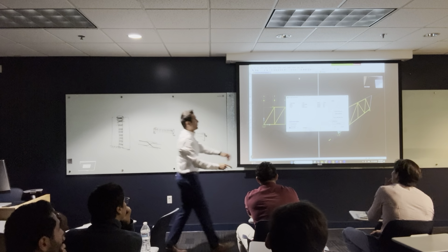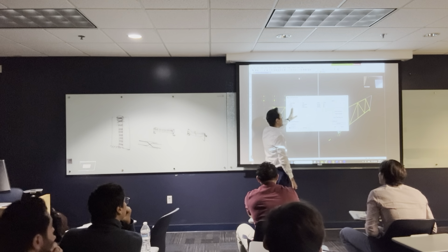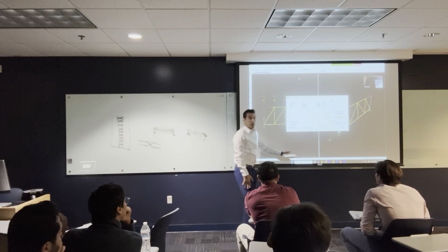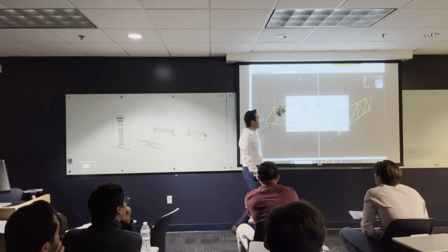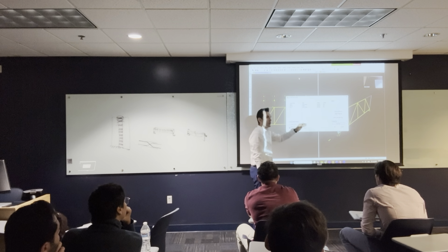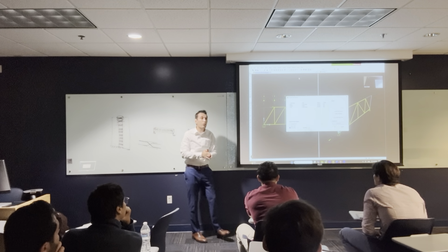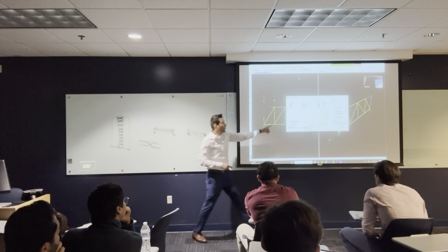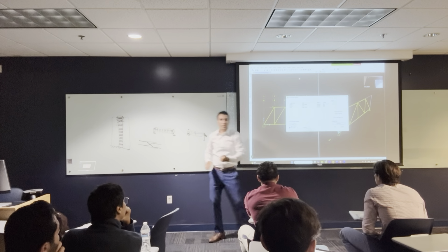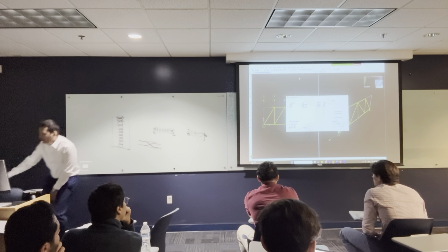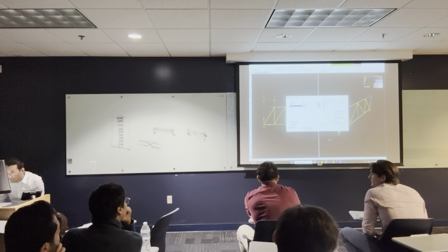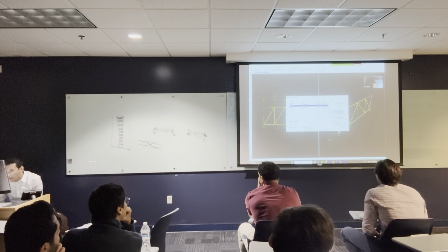What are these questions? It is going to ask you, do you want to run all these load cases? Do you want to run the dead and the live? And there's a load case called modal, which is a vibration case we use for seismic, and we don't need it right now. It takes more time than these two. So I'm going to escape the modal. I'm going to say, don't run modal.